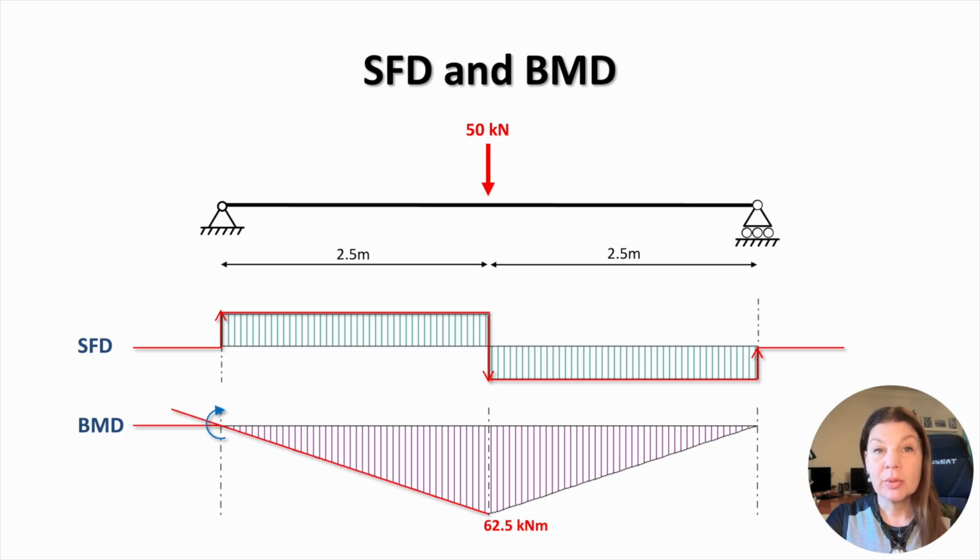The part of the beam between the left support and the concentrated load at mid-span is not loaded by any external load. Here the diagram continues as an inclined line. At mid-span, the concentrated load makes the diagram change direction again. Since the concentrated load acts downwards, this change in direction occurs counterclockwise. The part of the beam between the concentrated load and the right support is not loaded by any external force, and in this part the diagram continues as an inclined line.